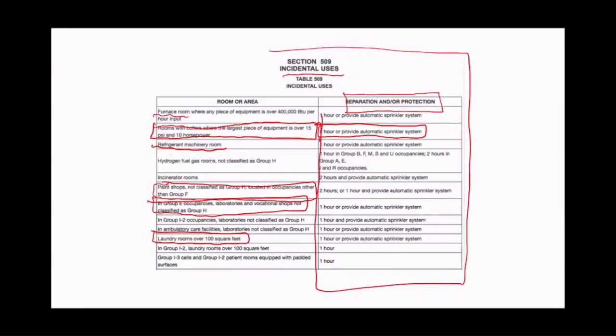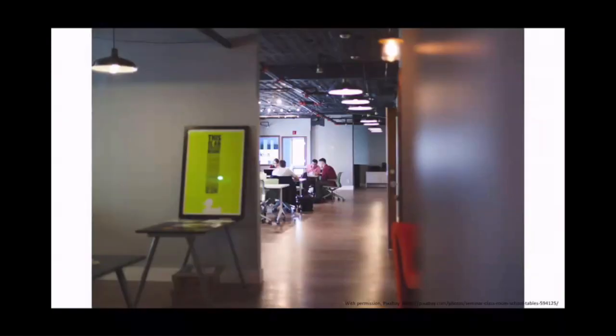Now, this is pretty specific. So if you don't happen to have one of those adjacencies, then you have to go through one of the other three paths. So if behind this wall was not something as specific as a boiler, let's say it was just a storage area. And let's say it was a storage area that was less than 10% of the total area of the floor. And let's say it was a storage area that was used by the primary occupant, by the accounting office. So they used it to store old files and records.